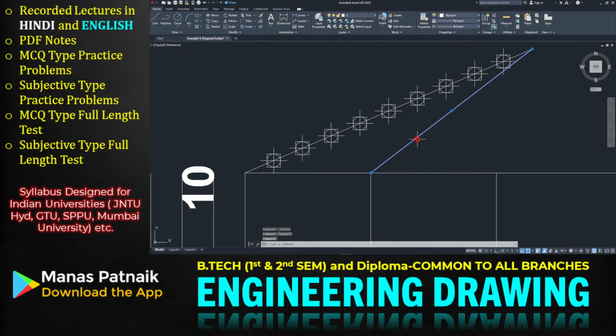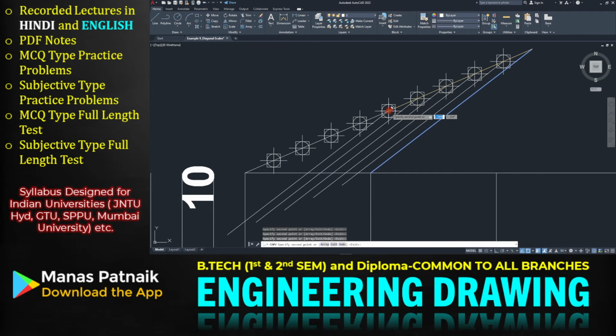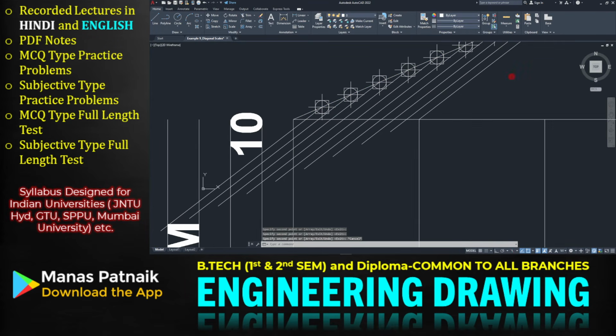Here we go. So let me select this. Let me make a copy. Copy. We have to go for base point. This is our base point. Click. Keep doing it. And you can see all the points have been exhausted. Now, we are going to use the trim command. TR is the shortcut. Enter, enter.